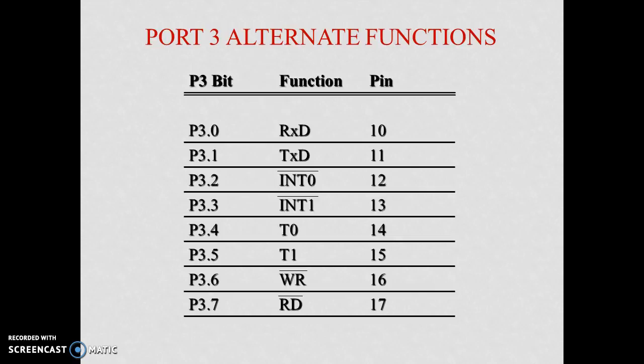There are some alternative pin functions for port 3. Port 3 is multiplexed. It can be used as I/O as well as transmit and receive. Similarly, there are the interrupts, the timer inputs, and write bar and read bar for external memory.